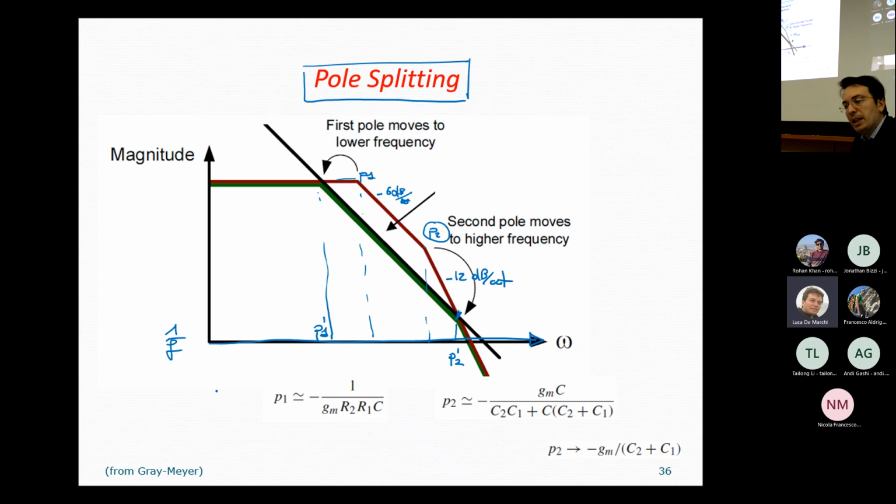If I7 is much larger than I5, then this quantity is larger than this one, and we can focus on the second term. Which is interesting because in this case, the negative slew rate is equal to the positive one.